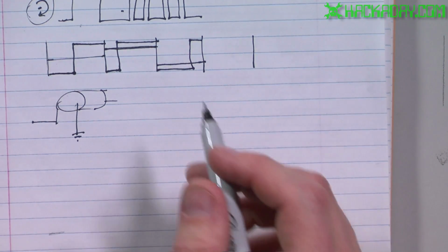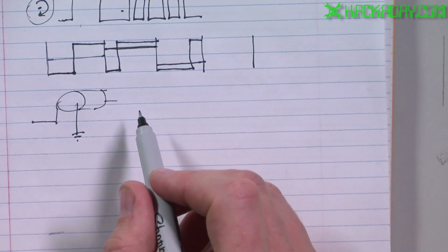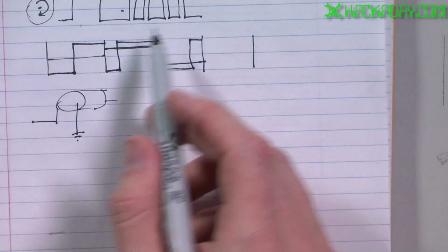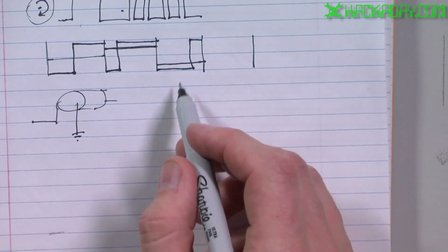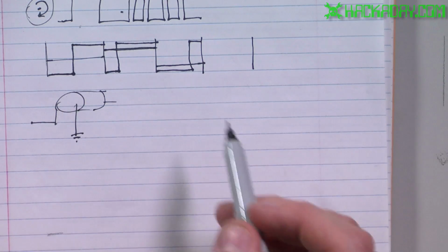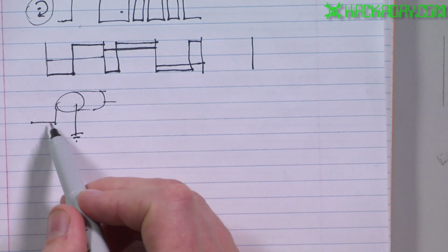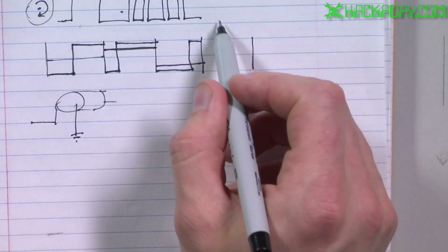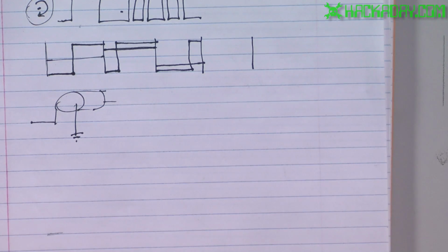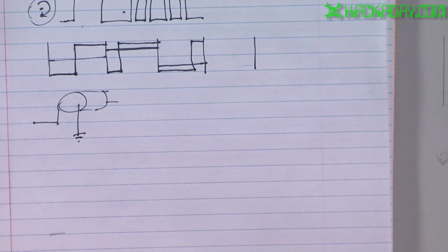Now, you could also do sign magnitude if you had, say, 2 pins that could pulse width modulate, and that could go into what's called an H bridge, and you could control the direction by pulsing one direction a whole bunch, and then when that's off, the motor is getting no power, it could coast, and then when you pulse the other one, it would go into the other lead. That's another way.